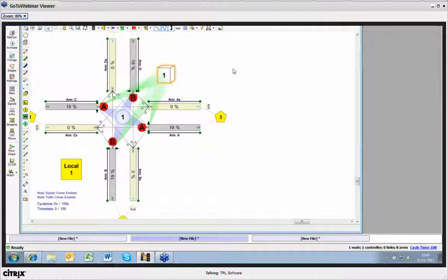There are certain benefits of using Transyt. Certainly, I think one of the benefits of using Transyt in this case would be the CTM model, being able to model the blocking back. So I think that would be the key message to get across there: if you're modelling the same scenario in Transyt, the ability to model the blocking back in CTM is probably going to give you the better answer if that's required of your network. But to compare the two answers is kind of an open question, really.